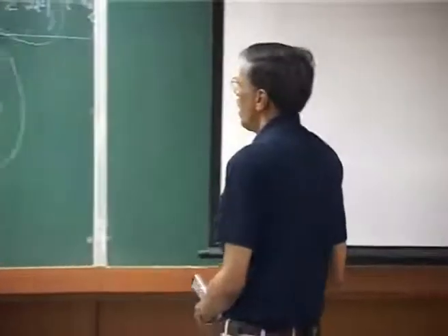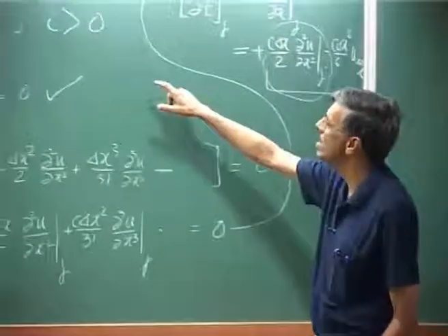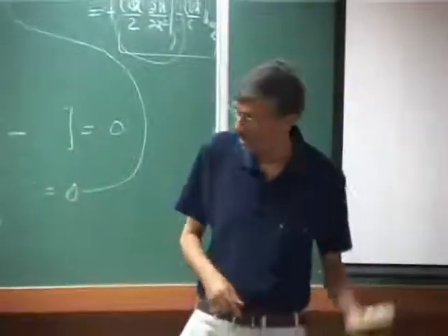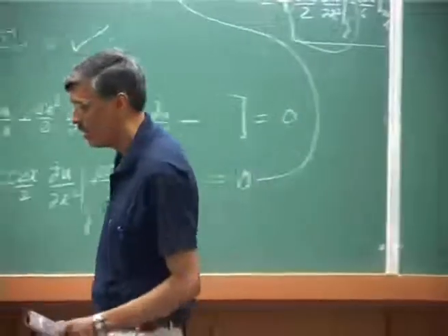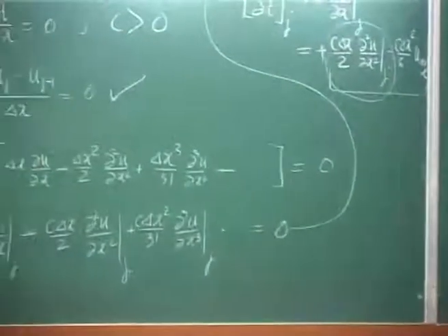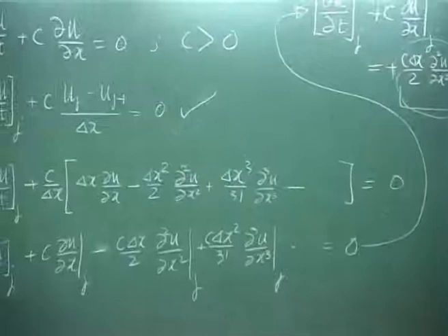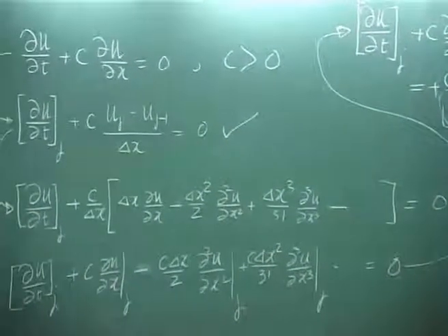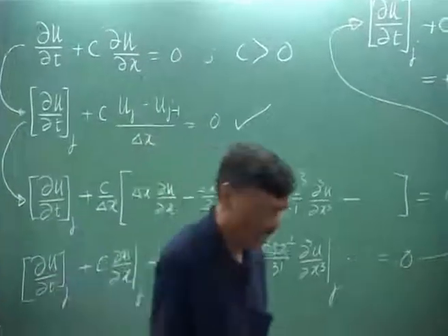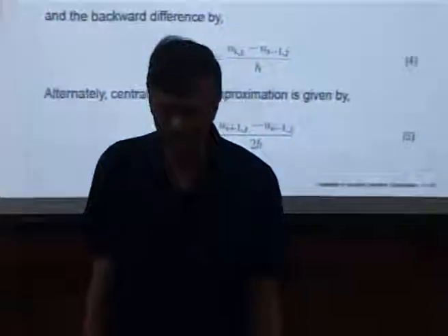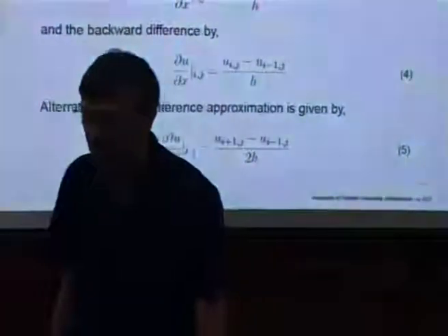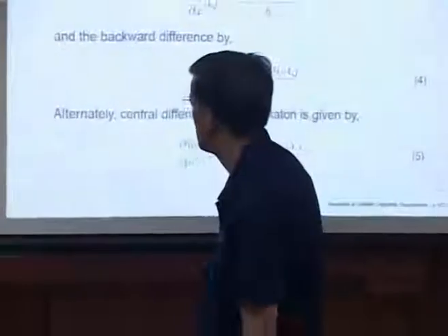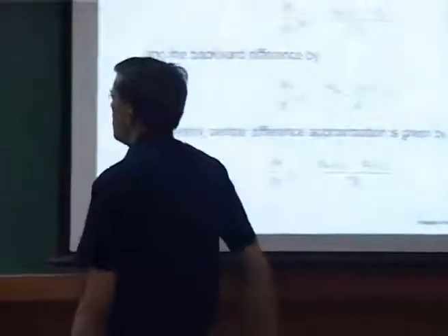However, you understand that taking a first order accurate method by the forward difference violates the physics of the problem and should never be attempted. Taking the backward difference form does not violate the directionality of the information propagation, but it surely does attenuate the signal, and that is something we should be worried about, right. We should not add numerical dissipation.